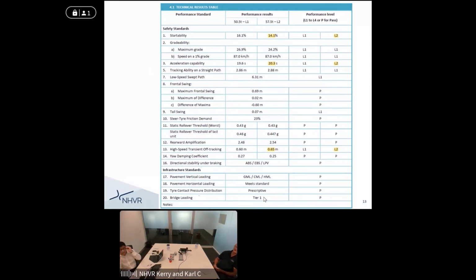So as you can see there, there's only a couple of things that would affect the performance of this vehicle. So we've got 4 things. You'd have concerns for this vehicle where there's grades greater than 14%, where you've got concerns about signal timing at intersections. So it's going to take a little bit, 0.7 of a second longer to cross. You have to consider whether that's an issue, or if it even applies. So if there's no application, again, if there's no steep grades, that doesn't even apply.